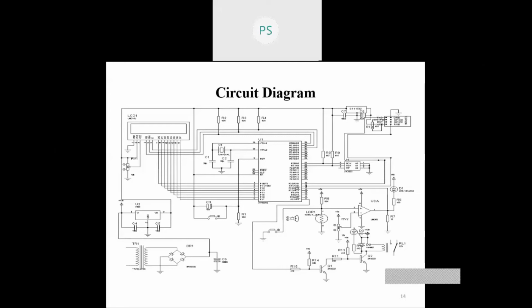So now we have connected an EEPROM to port 2 of the microcontroller. The EEPROM has 6 pins: SDA, SCL, WP, A0, A1 and A2. SDA and SCL are connected to port 2.0 and 2.1 of the microcontroller. As SDA and SCL are open drain, we must pull them up to communicate with the EEPROM. So two pull-up resistors are connected between VCC and the EEPROM.